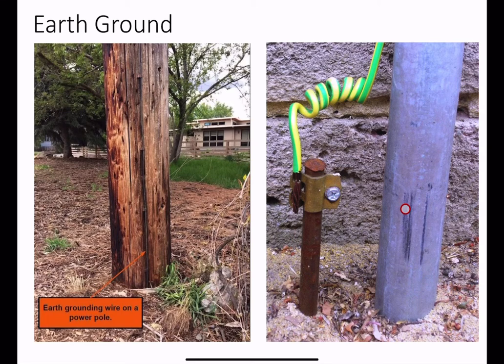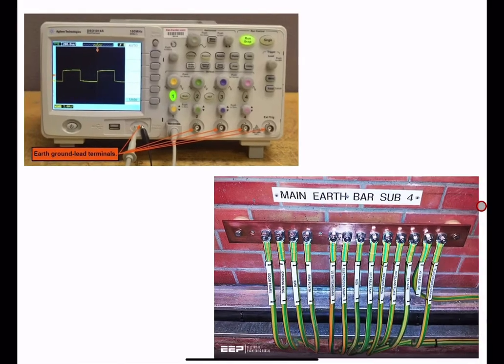So the other source of unwanted currents may occur due to malfunction of devices, short circuiting, or anything. So for safety reasons, all those electrical appliances in a building are connected to a ground plate. Like in this oscilloscope, the outer shell of the BNC connectors are considered as ground lead terminals, and this one is also for the probe. This is also ground.